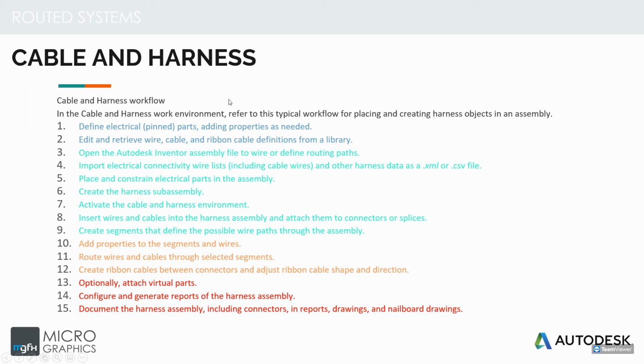But the main idea behind this workflow is that you would prep your tool, prep your parts, create your assembly, and then give them properties or values to make them more detailed and legible for the next person who's going to understand your diagrams. And then you can furthermore work on that with stuff like virtual parts or generating reports and nailboard drawings, etc.